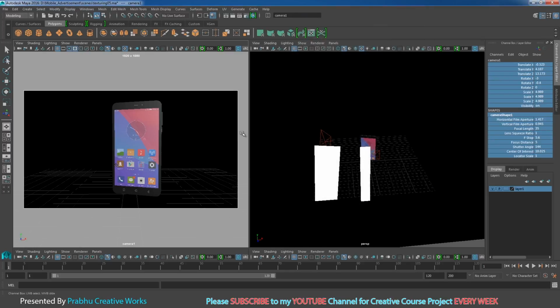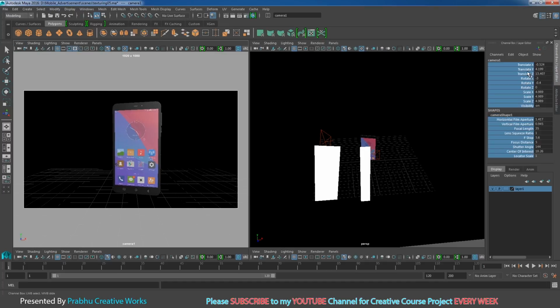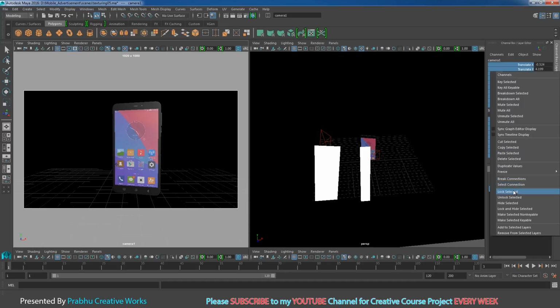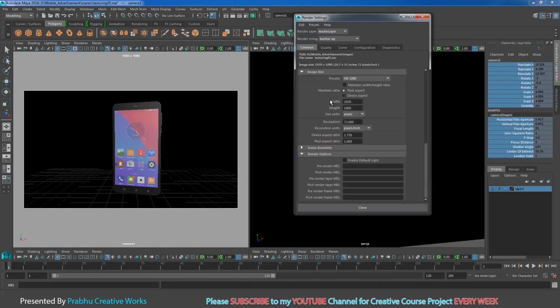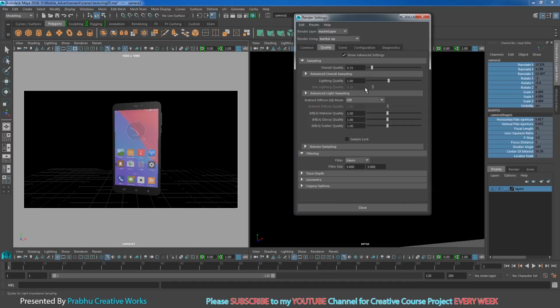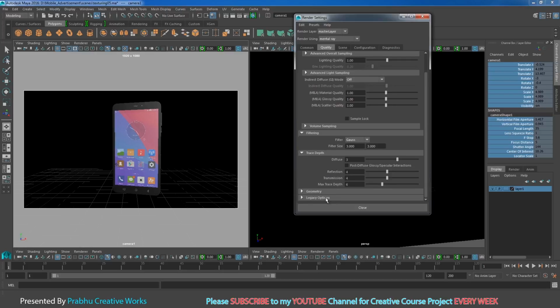So like this. So I will zoom out a little bit further. So go to view, select cam. So I will select all my values and choose lock selected. So I select my view and go to render settings. So here go to the quality tab. So go to trace depth option, legacy option over in the bottom side.